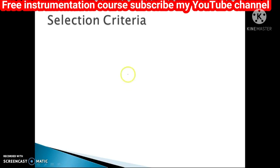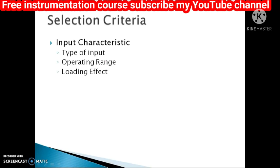Let's look at the selection criteria for transducers. When we need to decide or choose which transducer to use, there are some basic selection criteria which we should know. The first criteria is the input characteristics, like type of input, the operating range, and the loading effect. By the type of input, we mean the input quantity to be measured, whether it is temperature or distance or the quantity or amount of light.